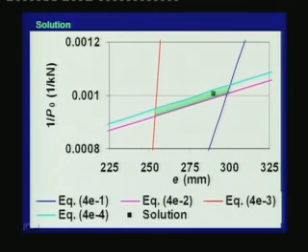Thus, this graph explains the application of the Magnel's graphical method for the type of section which has been selected for this particular problem, and the prestressing variables P0 and E that have been designed for this type 1 member. In fact, it lies in the acceptable zone, and hence these values can be used since they satisfy the stress conditions.